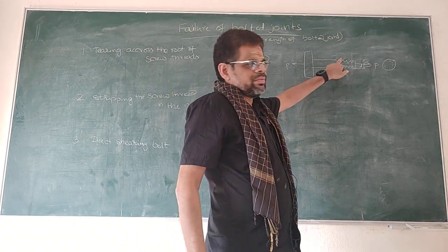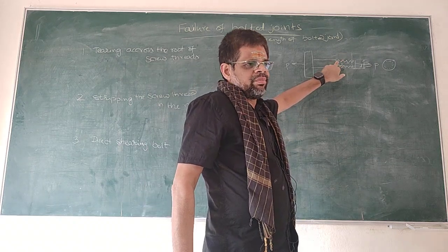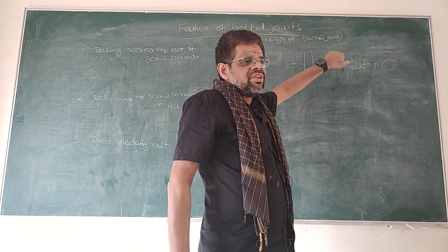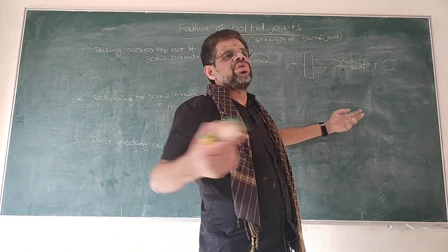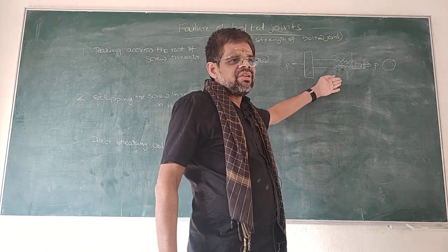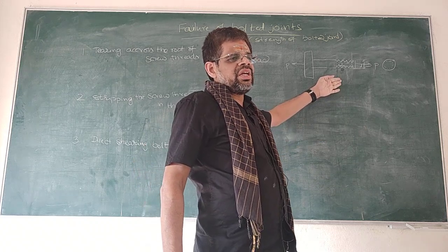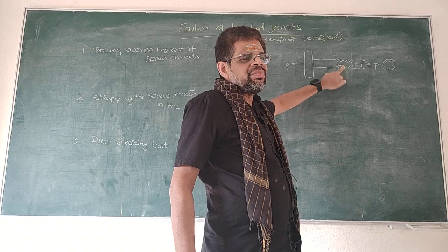So at the roots the area is minimum. That's why when it is subjected to tensile load, this bolt may fail at the roots as the area is minimum.